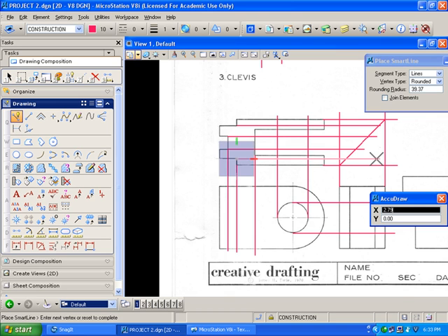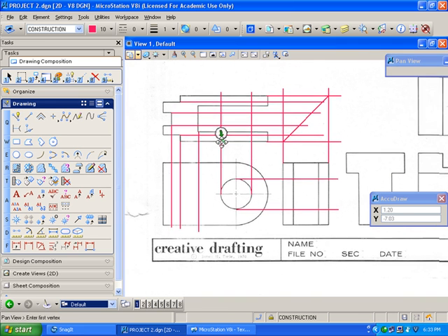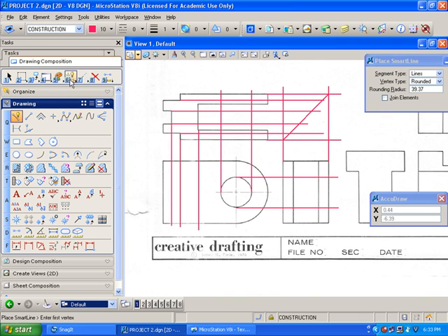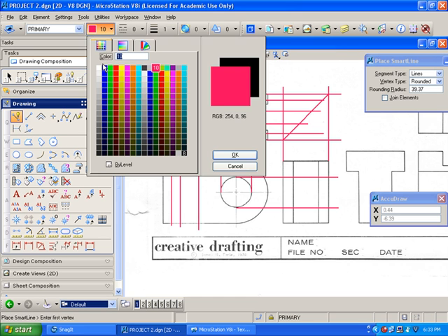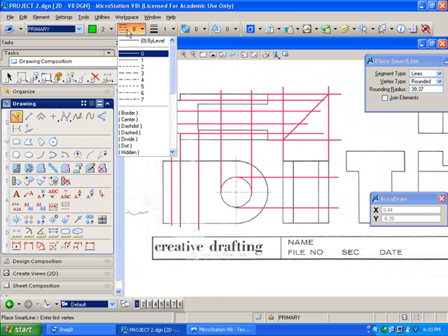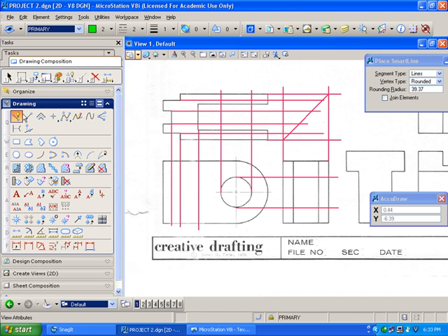We can actually simplify it a little bit now because I can go to my primary lines, change it to green, and these are going to be hidden lines style 2. I can just do a spacebar I right here and bring it straight down through. Spacebar I. That one goes straight through.